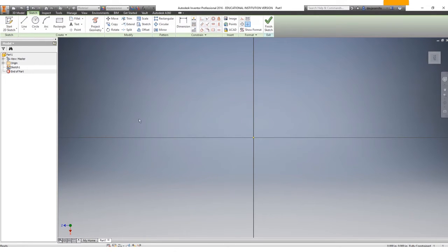And you'll know you're in a sketch right away, and I'll show you a couple things that will. Right away, it actually made it 2-dimensional. So now we're back to like AutoCAD. It's flat. You can see the screen is different. You have your center point and I suggest you use this all the time, okay? So this is the middle of the axes, right? And right here it's showing you what you're looking at. So the y-axis is right here, this dot. We're looking down like if we were a bird up on top. Okay, and this is the z-axis, and this is our x.